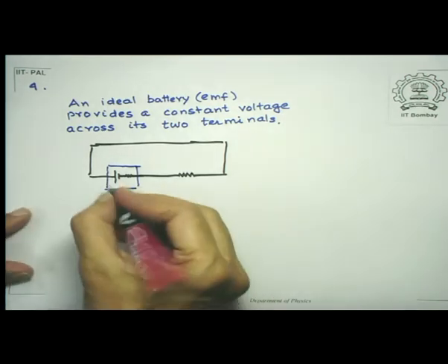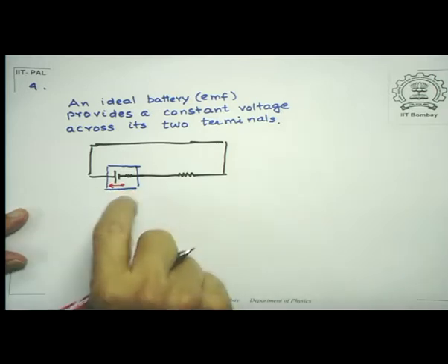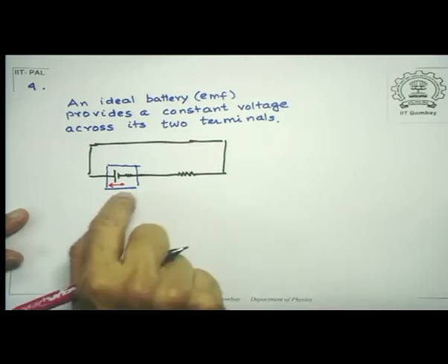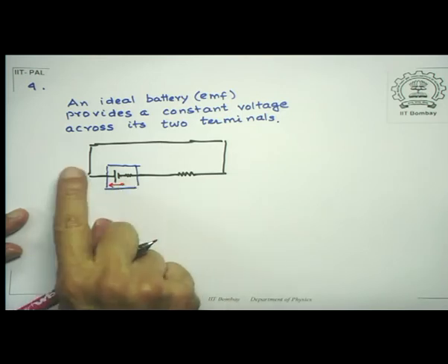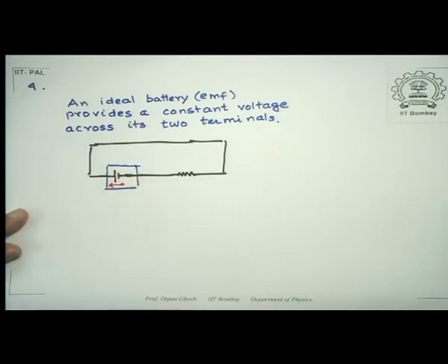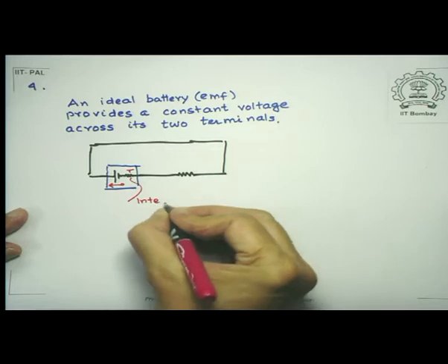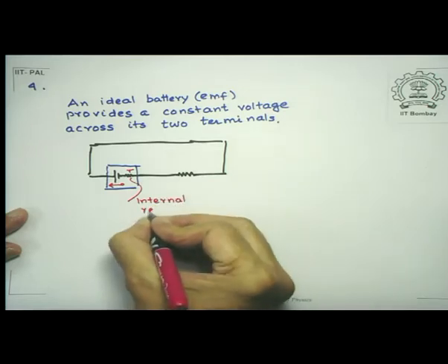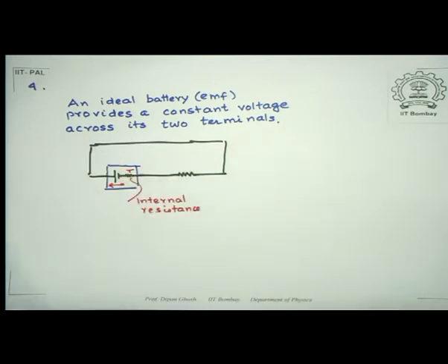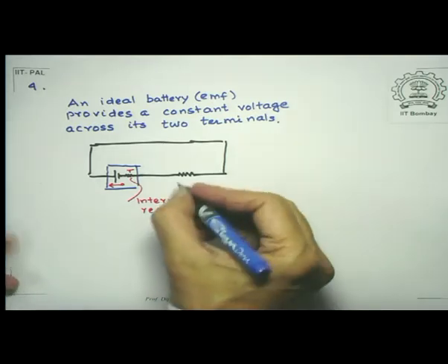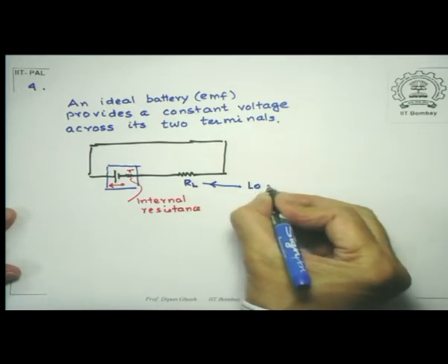What is frequently done in electric circuits is to do this type of a mark with a little circle at the base to indicate I am talking about an EMF direction, that is the direction in which the voltage increases from the negative terminal to the positive terminal, and there is a little internal resistance there. So this is your representation of the battery. The outside circuit RL is what is known as a load resistance, because that is the load that the circuit bears.